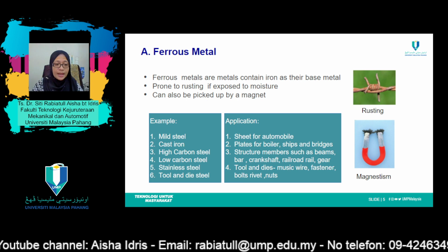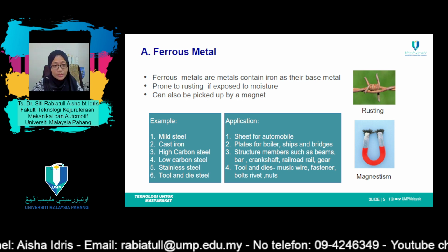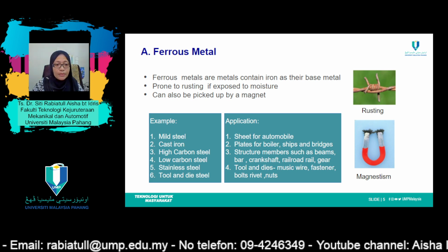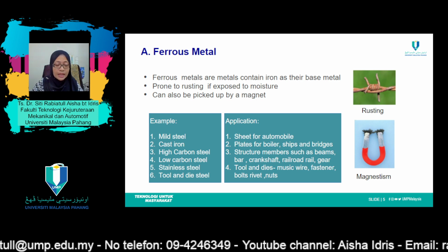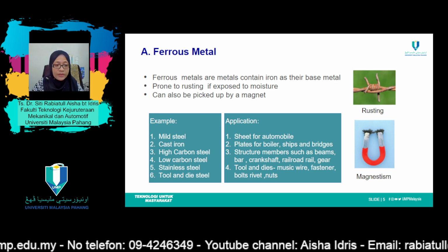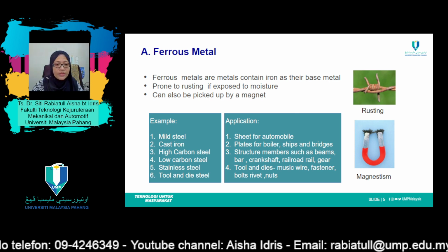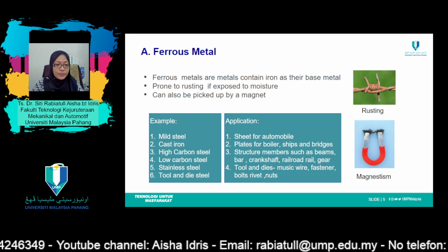Number two, metallic iron and steel alloys may be produced using relatively economical extraction, refining, alloying, and fabrication techniques. Number three, ferrous alloys are extremely versatile in that they may be tailored to have a wide range of mechanical and physical properties. The principal disadvantage of many ferrous alloys is their susceptibility to corrosion.